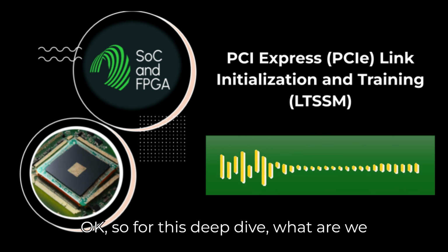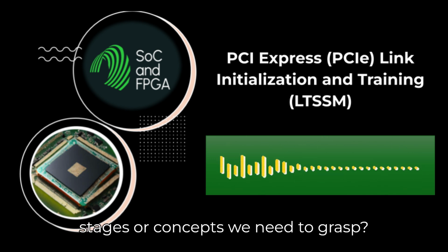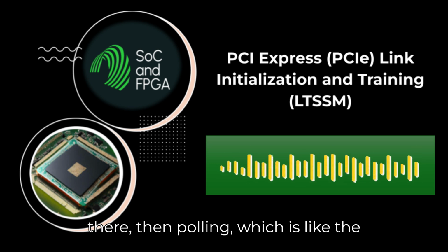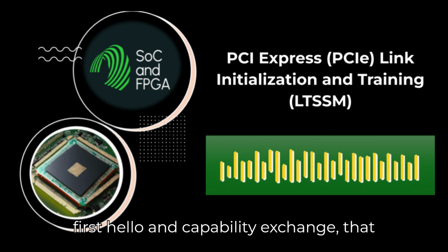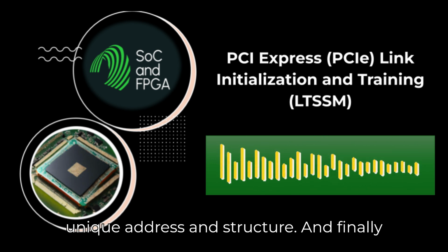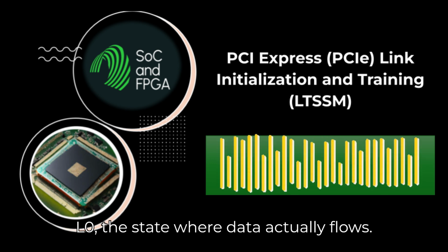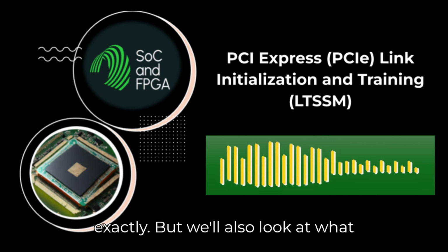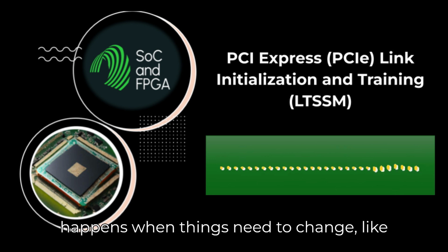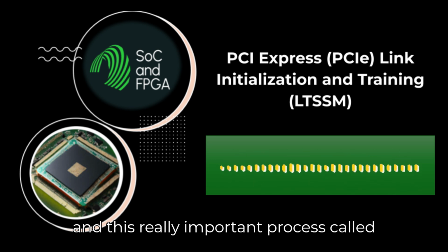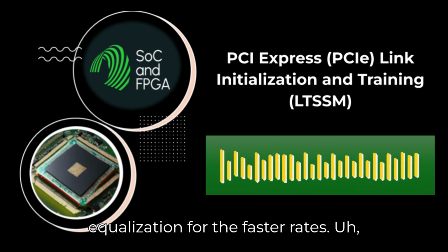Okay, so for this deep dive, what are the main stages or concepts we need to grasp? We'll trace the journey, starting with just figuring out if someone's there, then polling, which is like the first hello and capability exchange. Then configuration, where the link gets its unique address and structure. And finally, L0, the state where data actually flows. L0, the golden state. Exactly. But we'll also look at what happens when things need to change, like recovering from errors, changing speed, and this really important process called equalization for the faster rates.